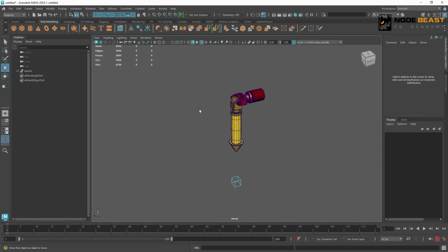A core rigging concept here is keeping the aim constraint's driver object position, while changing the up reference object to achieve rotation of the driven object on a single axis. By combining this method with our aim constraint method itself, we can achieve some interlocking effect between different parts shown in our example, moving together. This rigging approach is very common in our work, especially when we are doing some relatively complex mechanical rigging. For example, a very common type like a robot.